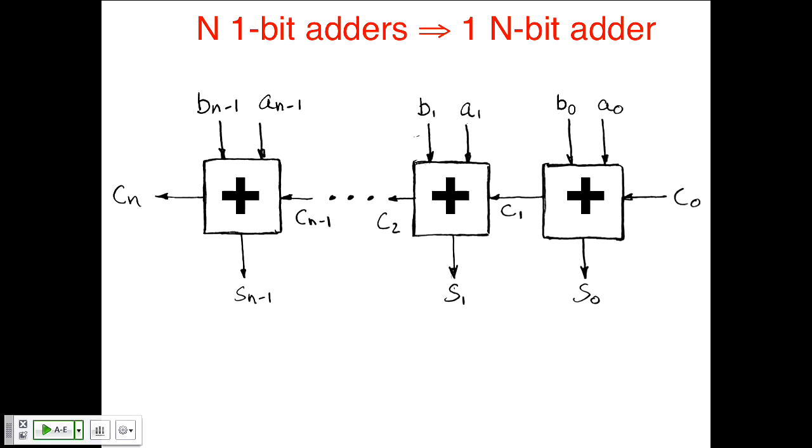So remember, when I set these inputs, I throw some switches inside here that connects these outputs to power or ground, depending on the combination of these values. This input will then set the switches in here, along with the switches that are already being set by these signals. And so what will happen is these inputs are already right at the beginning, but the carry signal is going to slowly propagate through here, sort of flipping the outputs to the correct state as the circuit evaluates. Right, and this happens as a wave in real time.